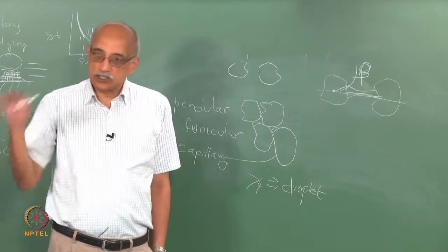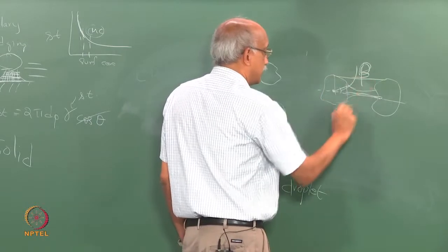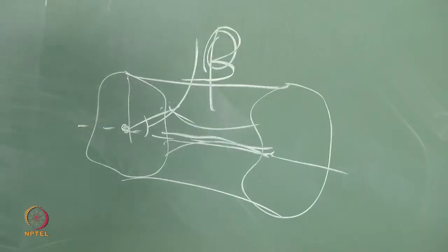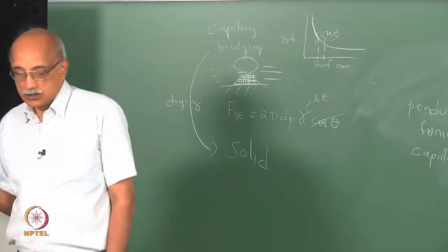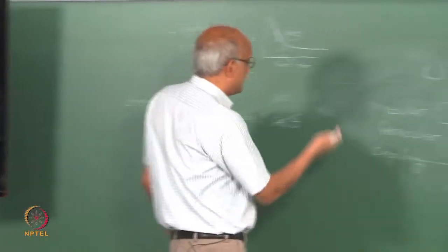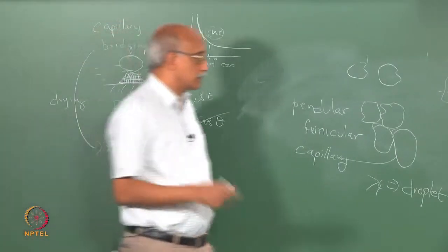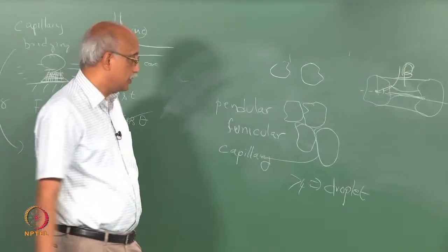Whereas as beta starts to approach 90, it says that the meniscus now encapsulates the entire particle. That is a very high level of cohesion. So the level of cohesion going from these states can essentially be correlated in terms of this. This is called the angle of cohesion. This beta is known as the angle of cohesion.